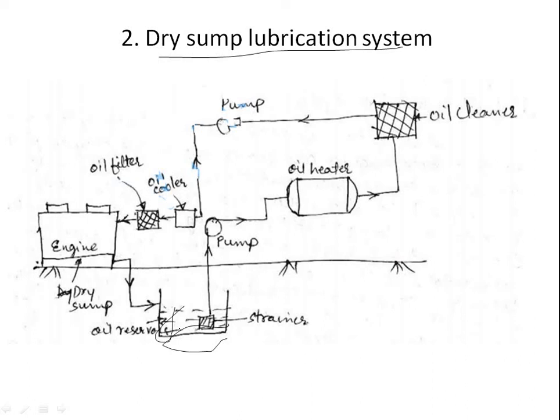Oil from the reservoir is pumped to the oil cleaner through this pump, via an oil heater. We use this oil heater in order to reduce viscosity.